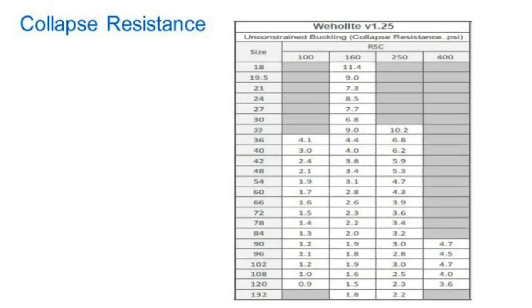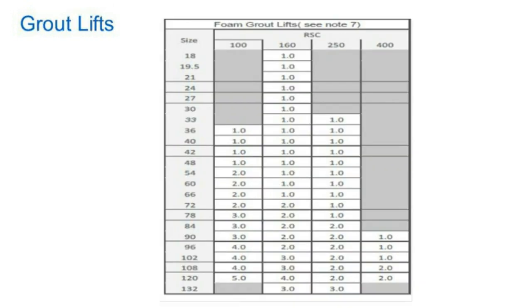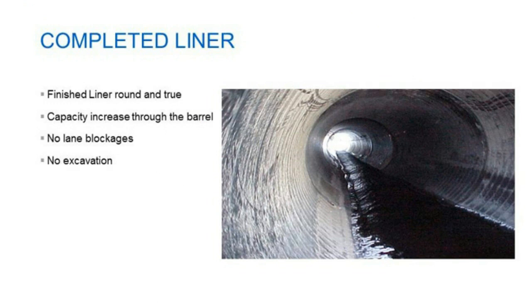As you can see here, a collapse resistance table can be provided. And as far as grout lifts, Uponor also provides recommended grout lift tables based on grout density. That grout density most of the time is going to be confirmed or specified by the engineer of record.